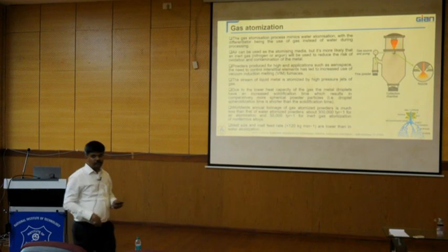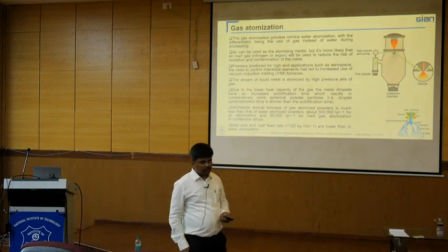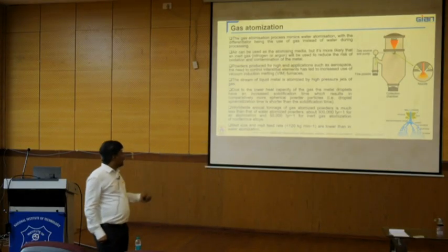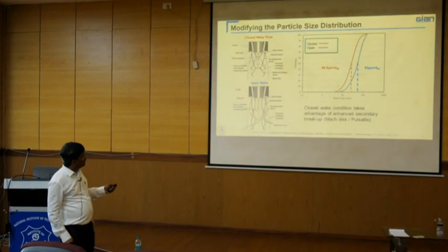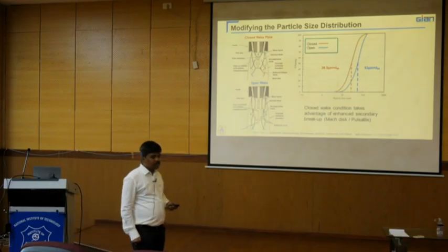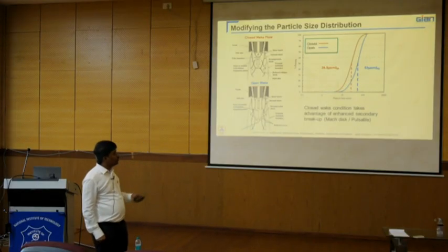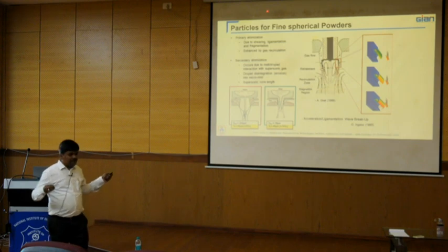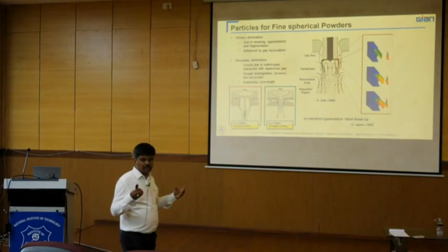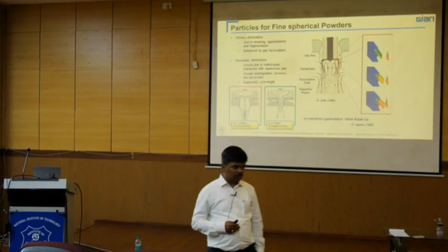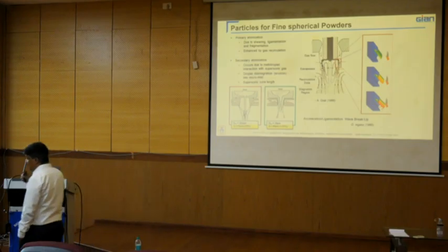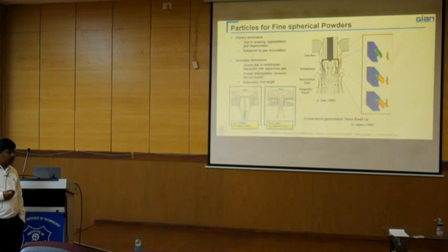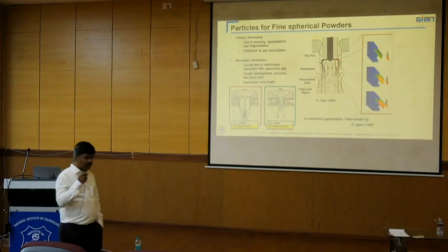Then what are the problems we face when we use water atomization and gas atomization processes? In the gas atomization process, we can melt and feed less than 120 kg per minute, and we get powder particles in the range of, I think, 100 to 500 micron size. But when we melt this, how do we control the powder particles? What is the rate of impingement, whether gas or water, at what rate we are impinging into that molten pool, the velocity, and the orifice angle, that is, how much inclination the water is falling onto your molten pool. With this, we can control the diameter formation of the powder particles.